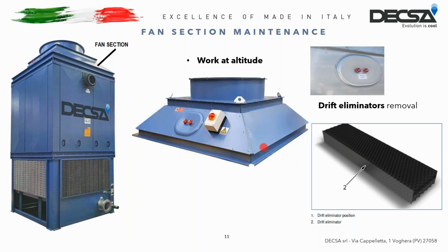Once the inspection door has been removed, you are in front of the drift eliminators, which must also be removed in order to check their integrity and verify that they don't have problems in terms of dirt and clogging.